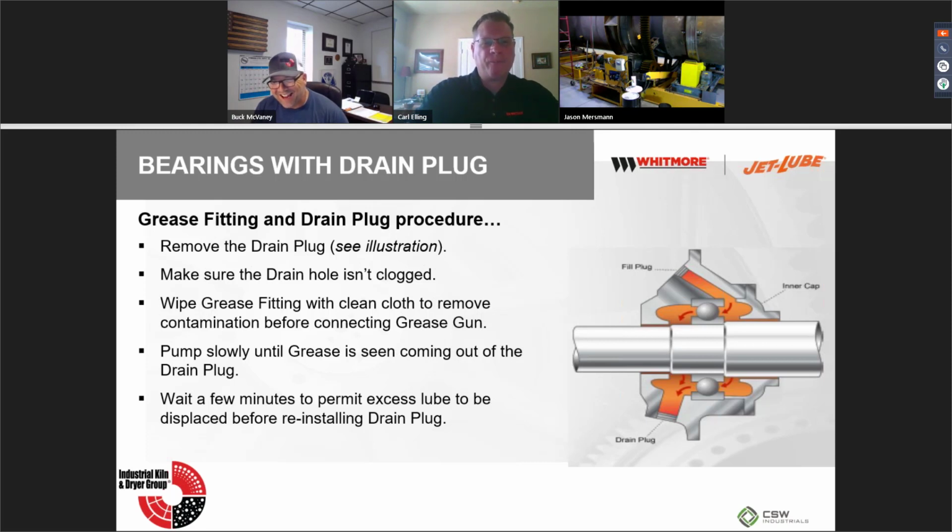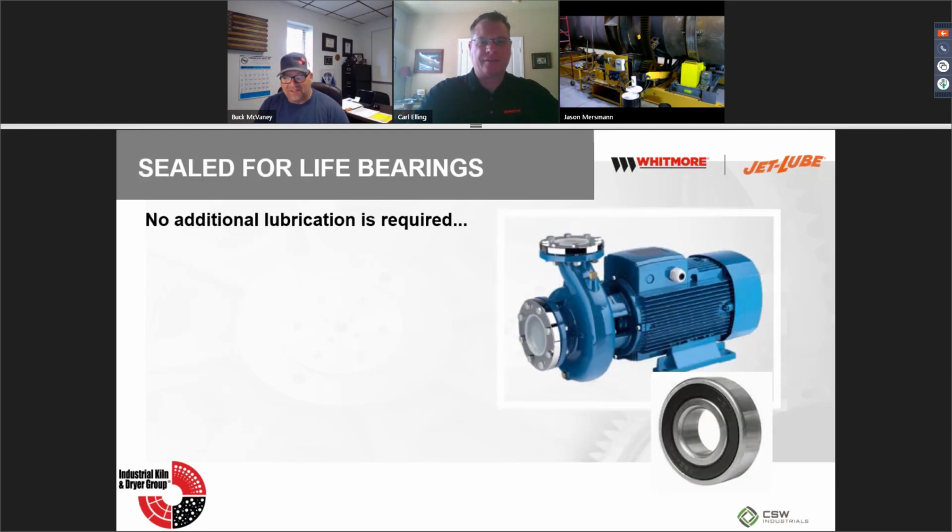All right, let's go. So this one I like. It's sealed. If you're a lubricant sales guy, you don't like these things, but I like them just because of ease of maintenance. So it's a love-hate relationship. You'll find a lot of these in your electric motors and stuff like that. So it's commonly found. There's not a grease zerk, so that's a high indication that there's not any application for that to apply grease to. So just FYI there.